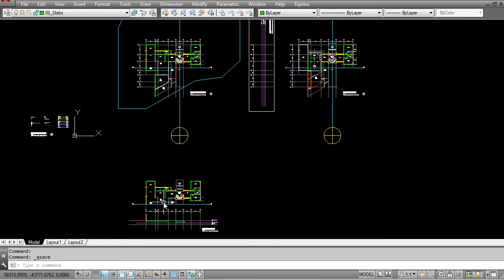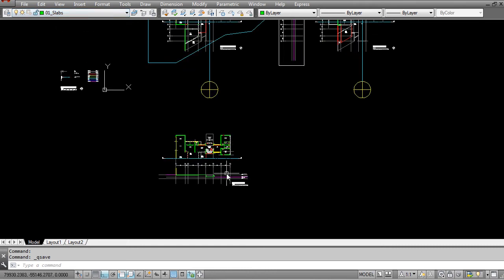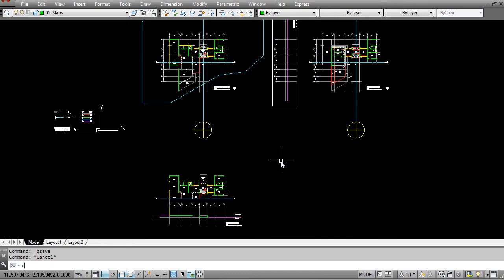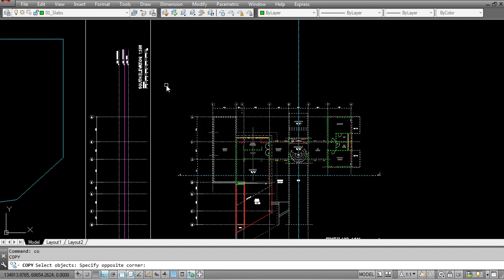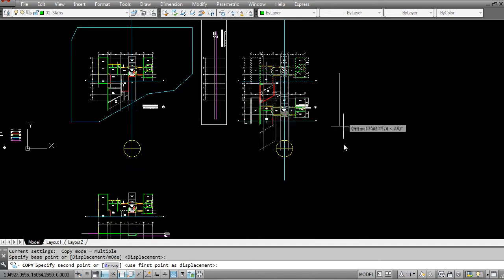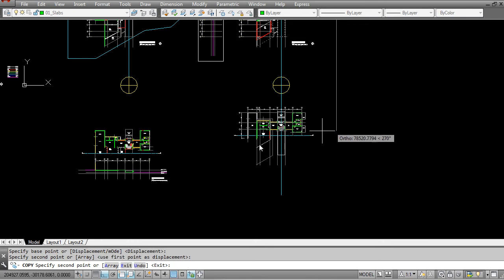So that is a nice tip that you can use, and the way that I learned that the hard way is that if you start turning or locking your layers on and off, you basically will start moving things around and you'll leave some layers behind inevitably, and then you will never know exactly where those layers are supposed to be placed and how they are supposed to be aligned, and basically everything starts to fall apart if you do that. So let's follow that rule now, and we are going to make a copy of this upper level, and we're going to do exactly what we did earlier by shifting it, using it as a reference.